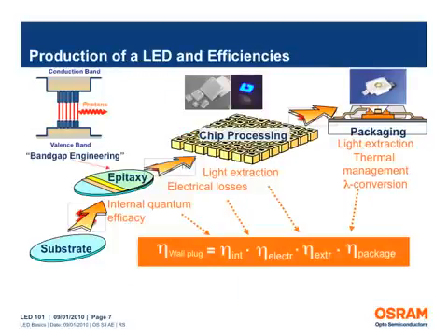To further improve the overall efficiency of the LED, optimization is required in all value-added steps, beginning from the substrate through the package. To fabricate an LED, we start with a substrate on which several epitaxial layers are grown atom by atom. After various chip processing steps, the entire wafer is diced into single chips, also known as dies. Finally, the small semiconductor chip is assembled into a package for mechanical protection and electrical, thermal and optical interface. To improve the overall efficiency of the LEDs, each of these manufacturing steps needs to be optimized.